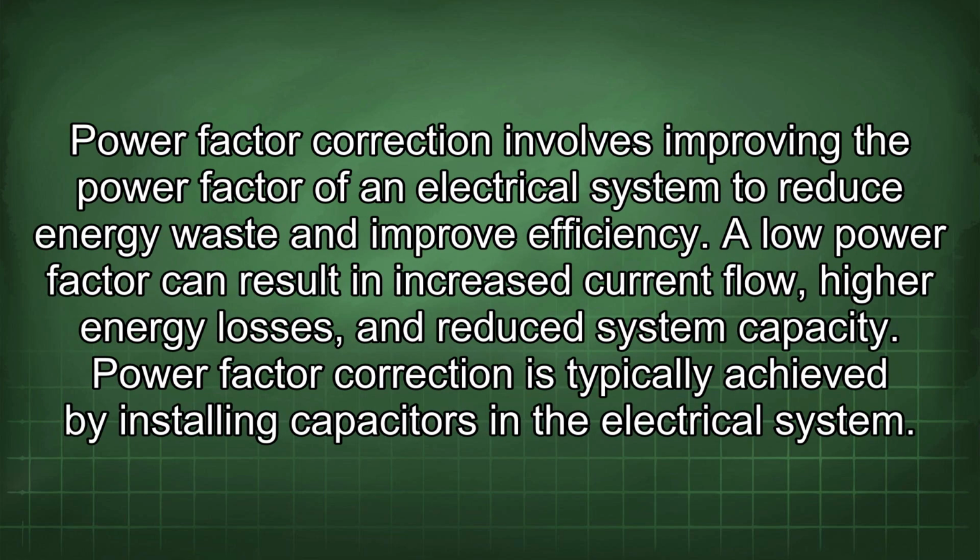Power factor correction involves improving the power factor of an electrical system to reduce energy waste and improve efficiency. A low power factor can result in increased current flow, higher energy losses, and reduced system capacity. Power factor correction is typically achieved by installing capacitors in the electrical system.